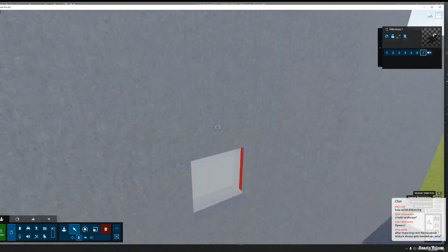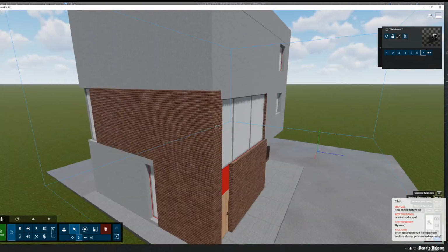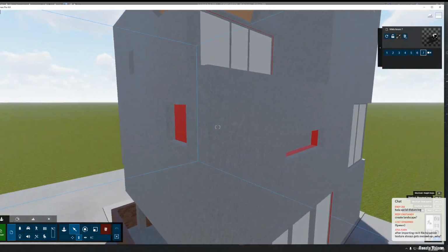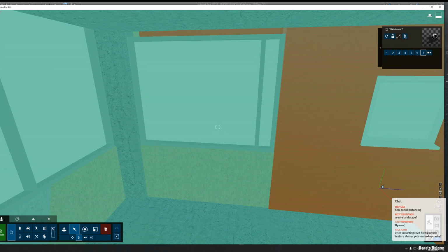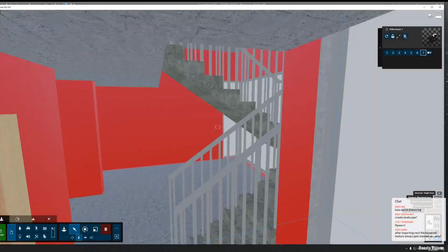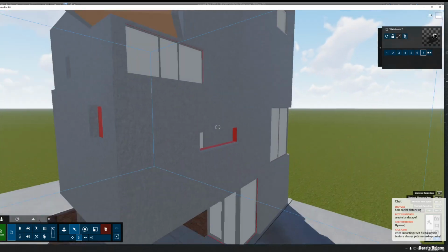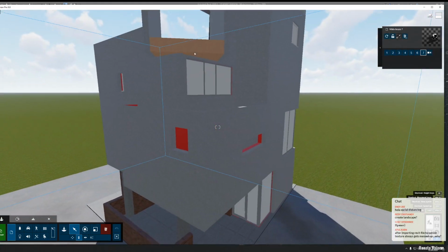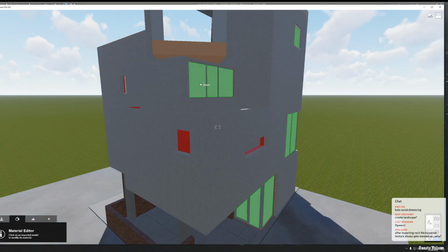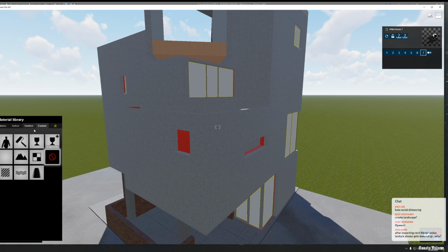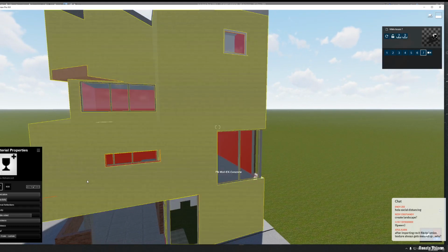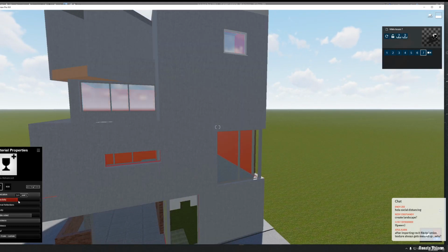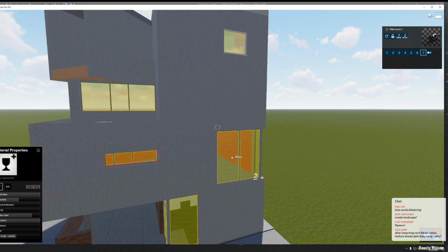As you can see, not any here, but it's okay. We don't have any red color outside, only here and only here. We will think about that later on, but for now everything is alright. So as you can see, our external color is as I want. Let's make, for example, material for our glazing. I wanna use this advanced glazing. Let's use it, as you can see, and I wanna have a reflectivity a bit more than the existing one.